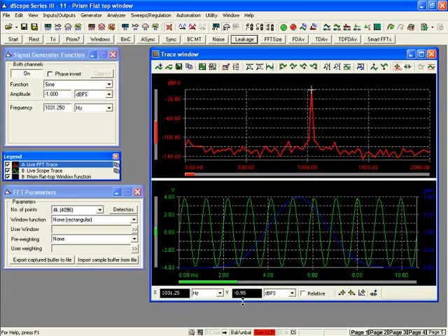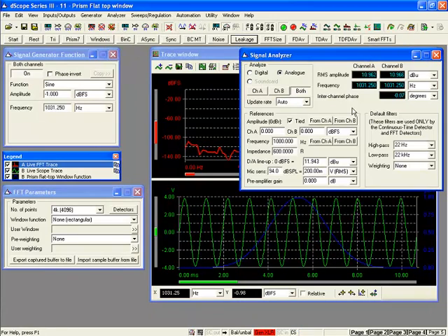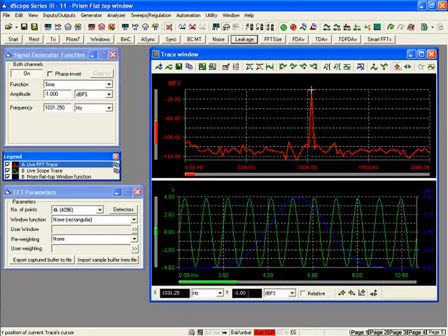My amplitude reading is showing me effectively -1 dBFS, and in fact that's just slightly off because my reference has drifted just slightly. So if we put 0.962 in there we go, we'll see that we have exactly -1 dBFS of energy at 1031.25 Hz, which is exactly what we'd expect.